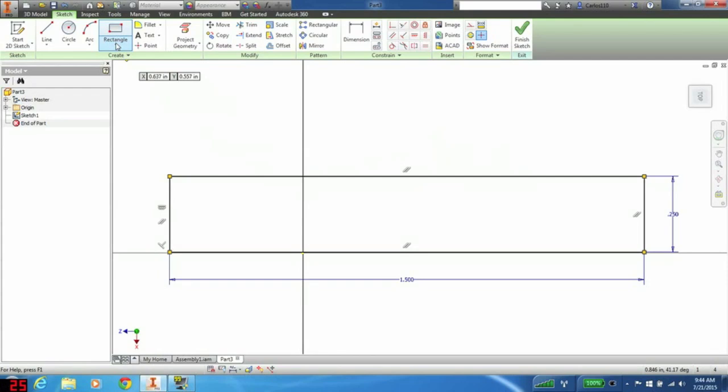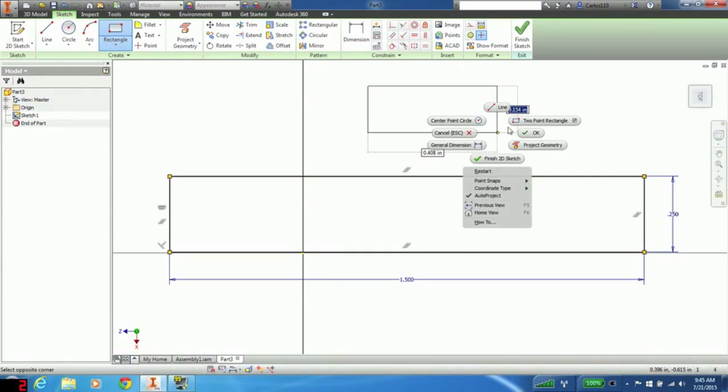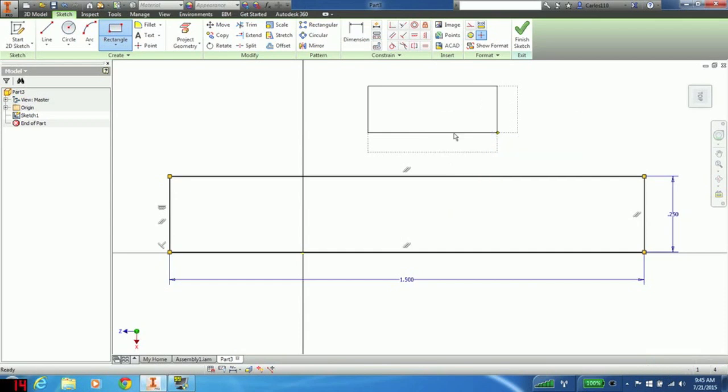Now, as you can see, our rectangle icon is still highlighted, and I still have the yellow first point dot following my cursor around. If I were to click again, I would start to create another rectangle. Now, I don't want to do this. I only want to create one rectangle. So I am going to right-click with the mouse, and now a new thing appears. It's a pie chart with a little drop-down menu. And we are just going to click Cancel, Escape, X. And that exits out of the tool, and now we have our rectangle in front of us with the proper dimensions set.